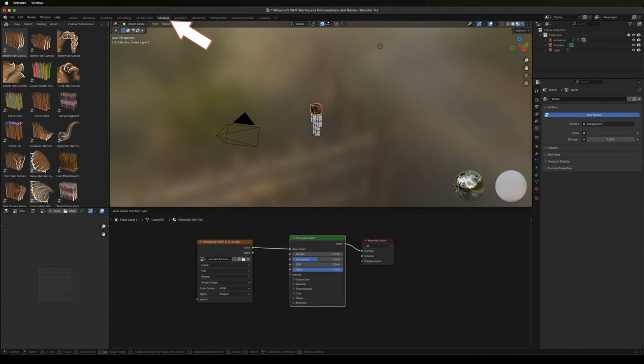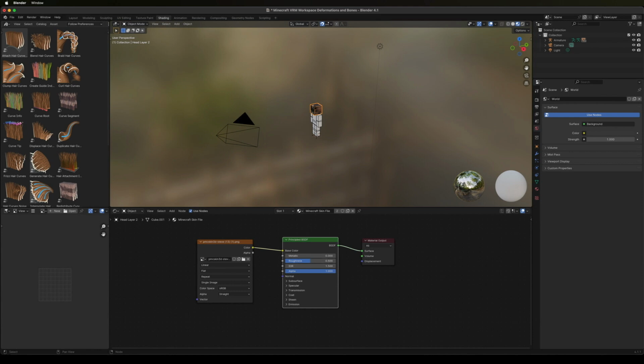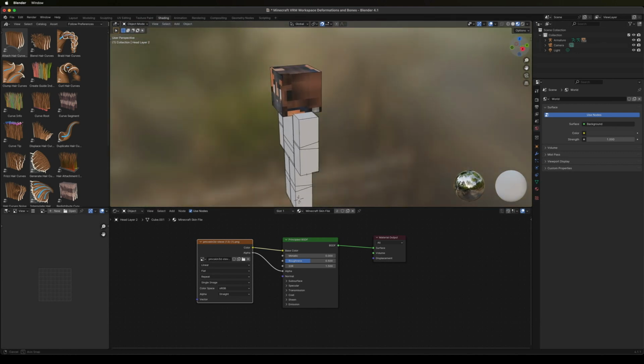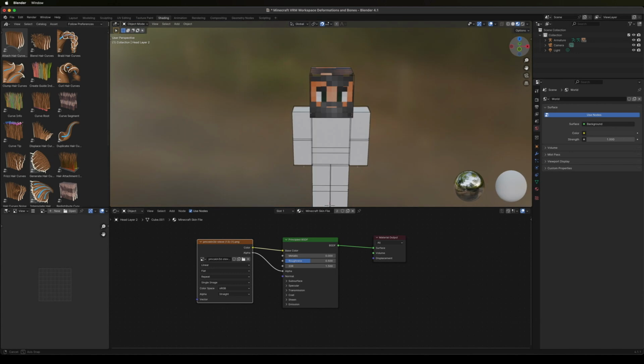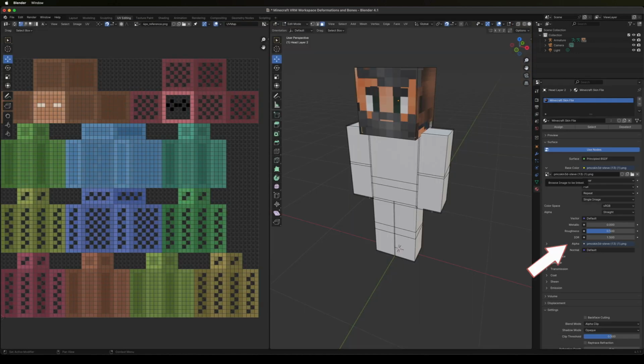we'll go into the shader editor, which is used to edit the materials for rendering. We're not really interested in much here, or even which rendering engine we're using, other than the node editor and the viewport immediately above it. Since we started with a principled BSDF material and linked an image for the texture, we can see in the node editor that the alpha nodes on both the image and the material have not been linked. We drag a connection between these nodes and can immediately see that the black transparency areas are now actually transparent by seeing the change in the viewport window. We can see the changes we just made in the shader editor in our Materials tab of the Properties editor. This would have been the other place to make the link change.